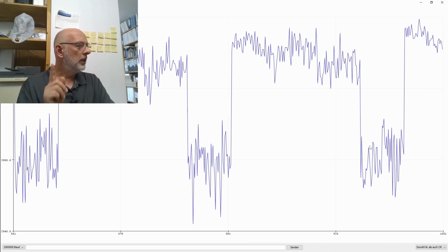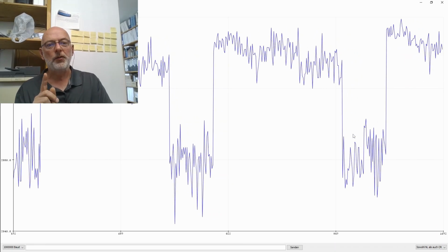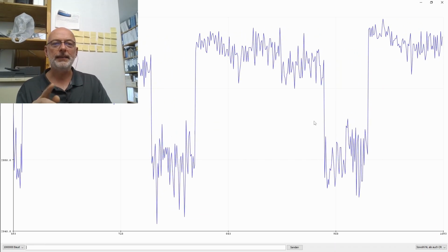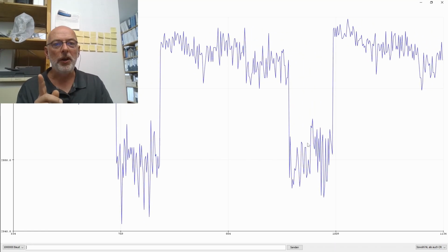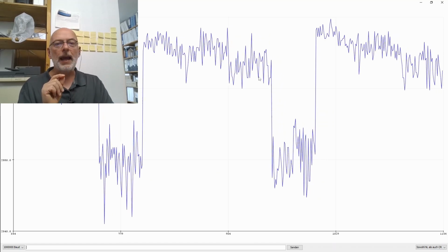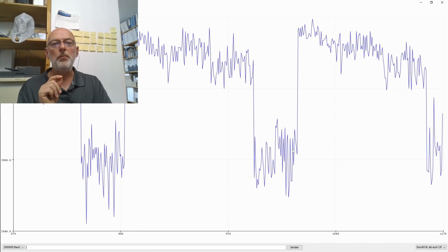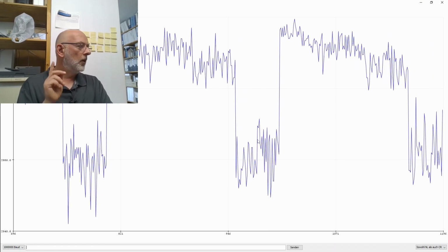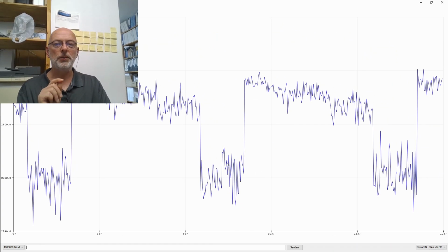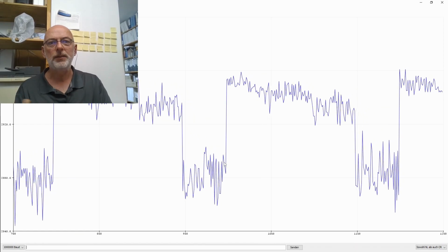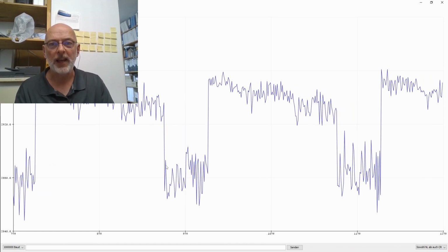And then we switch into that 800 Hertz mode. And two things happen. We have a lot more noise on our signal, and our signal value makes a jump. So be careful when using that 800 Hertz mode, which gives you a measurement, if you want, every 0.5 seconds.